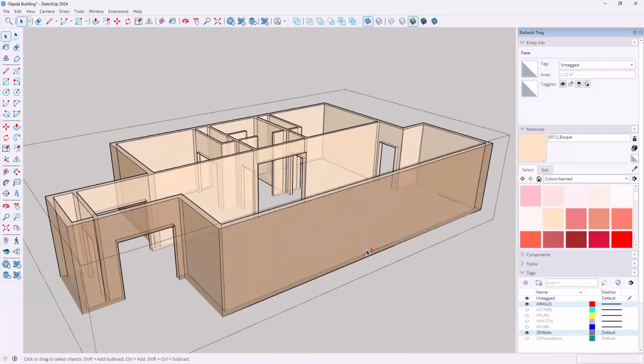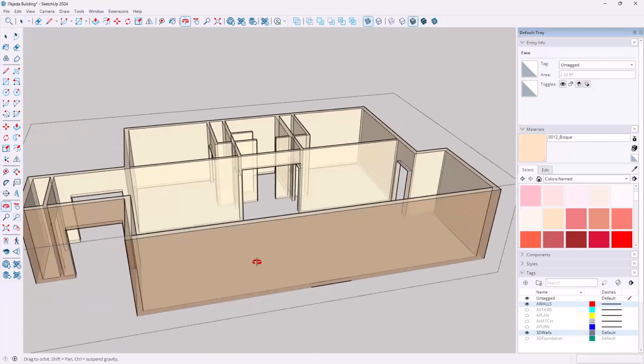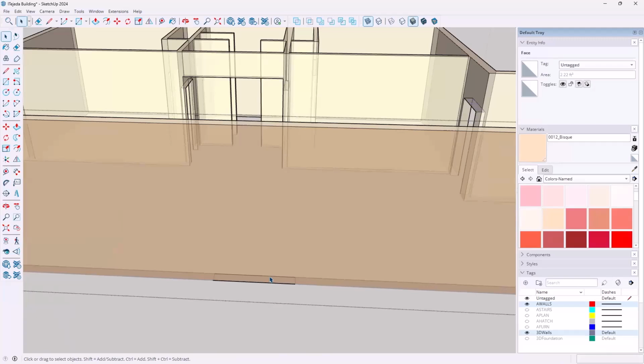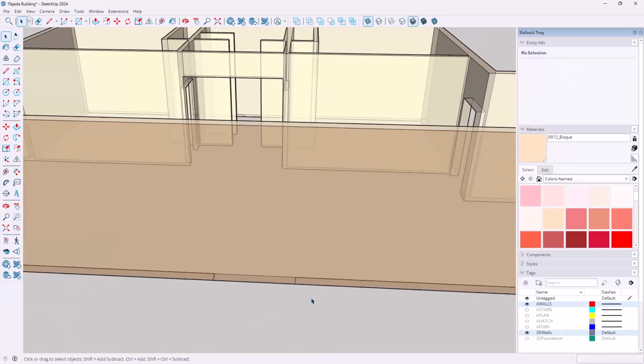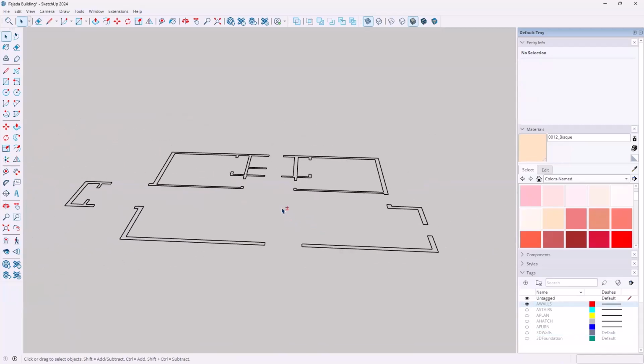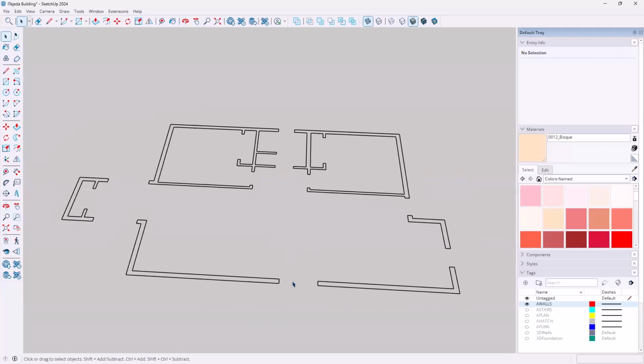And then you have your window openings. Now I'm going to place one window opening, but you will put in all of yours. I just want to show you how this works. So I've indicated on my drawing, and here, let me click away, and let me also turn off my 3D walls and turn on my walls. All right. I'm showing that I want to have a window here. I also have an opening here for that window. I guess I should model both of them to give you an example.